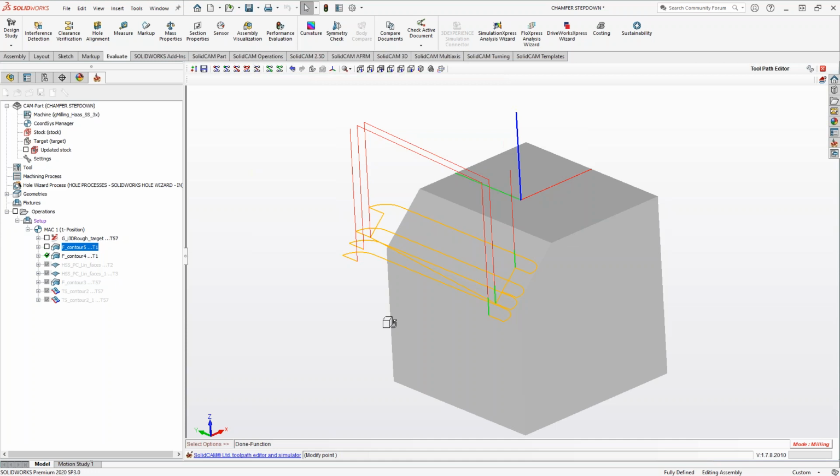So this would be a good example of your own self gouge checking. If the data is all there, all the data points are still there, but you need to trim out the bit of code that is causing the collision, or you've generated an entire toolpath and you have no other way to trim it using stock recognition or surfacing or anything like that, then you can come in here and manually edit all that. Applications of this could be things like maybe if there is a hole in that surface and I don't want to waste time cutting air, or I'm trying to avoid a gouge, I can easily just do some trimming of my own, rerouting the toolpath, a lot of that kind of stuff.